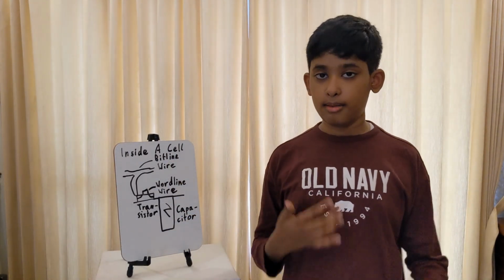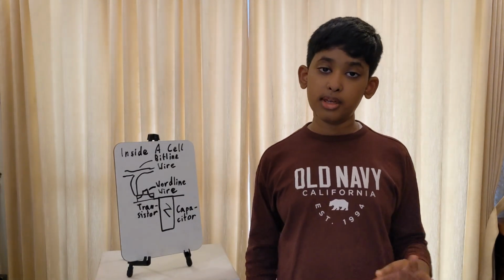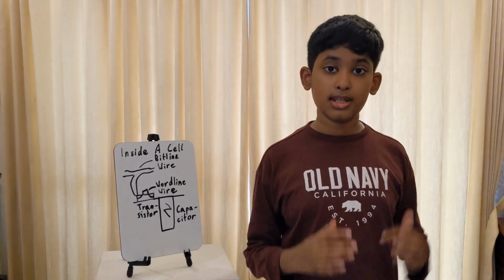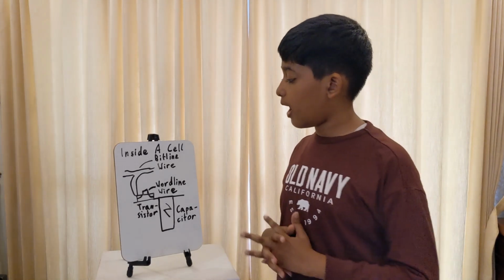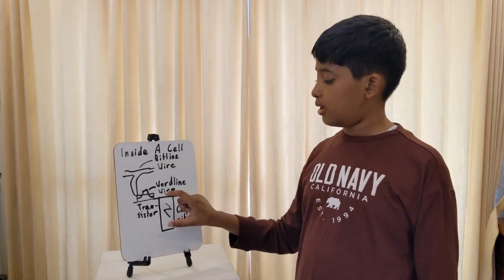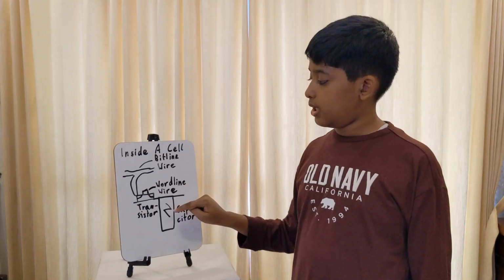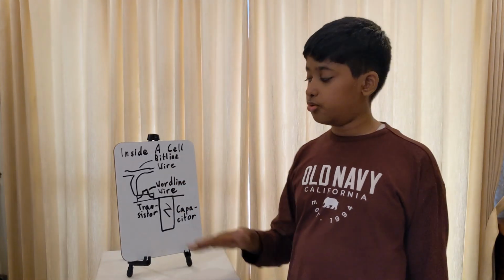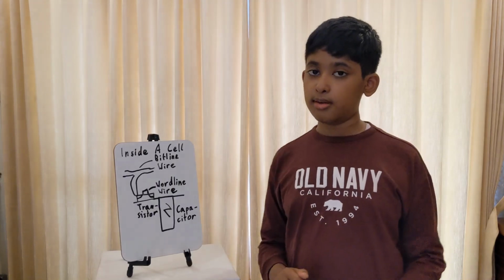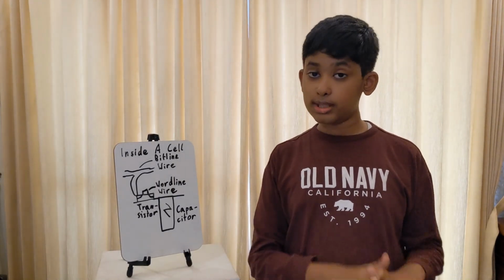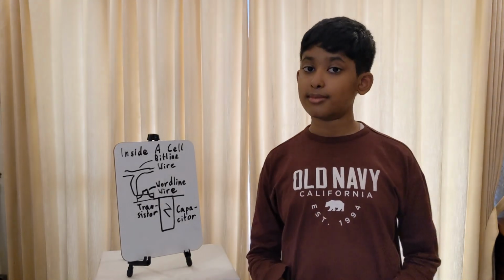This might seem a bit flimsy, but when we go to the grid layout, we'll discuss how amplifiers help us deal with this. For now, just remember that these capacitor cells are read and written through this bitline wire, and this wordline wire controls whether we're reading, writing, or doing nothing at all with this capacitor.